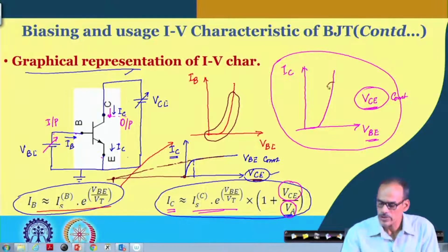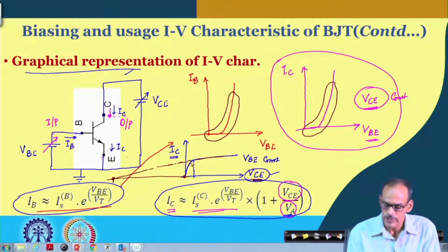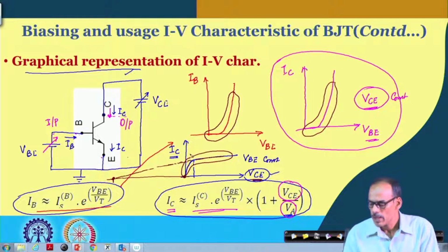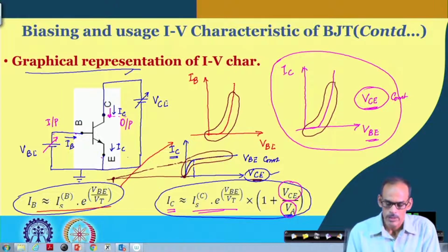Likewise here also we can see a highly nonlinear effect. Here also, if you push the device into this region beyond the active region, of course, we can see the highly nonlinear part. But whenever we will be focusing on amplifier, we may be keeping our signal well restricted within a narrow range, maybe somewhere here, and probably around that, whatever the slope of the characteristic, that may be important.